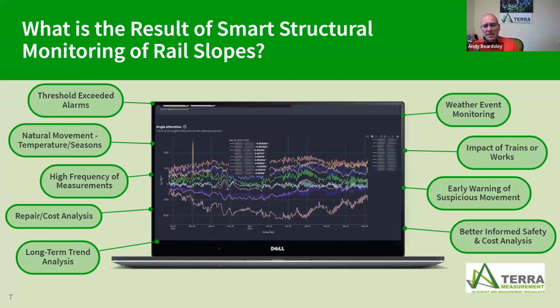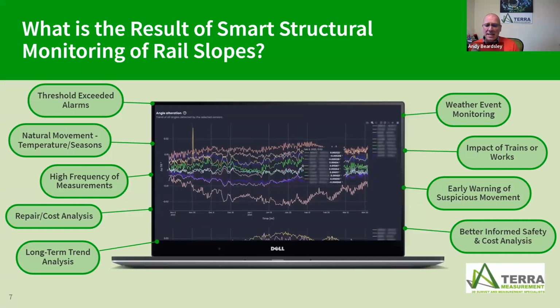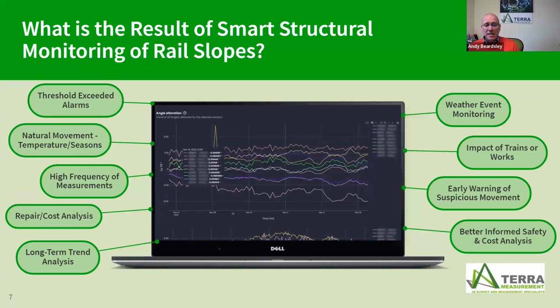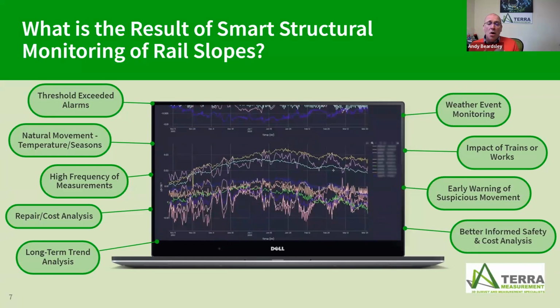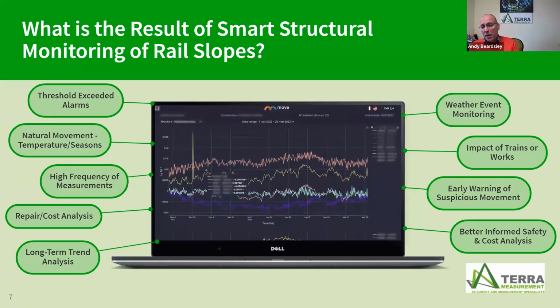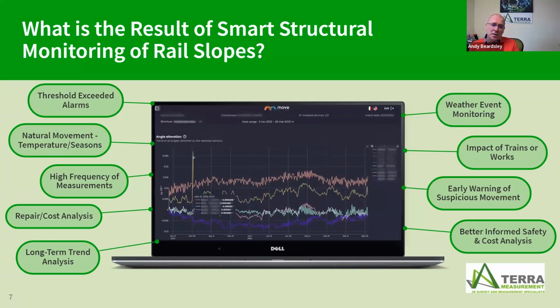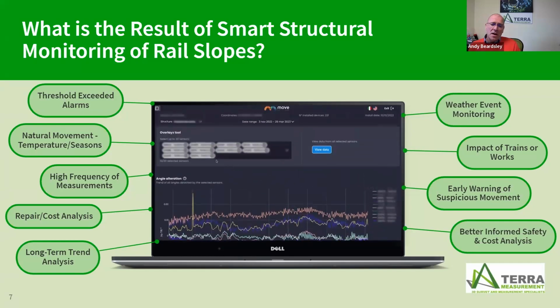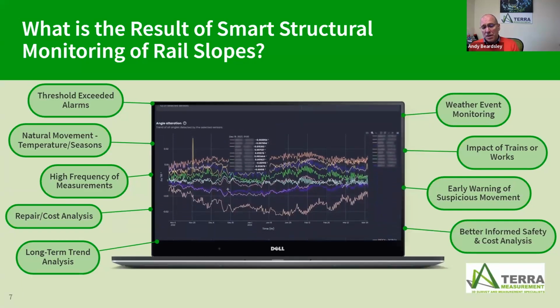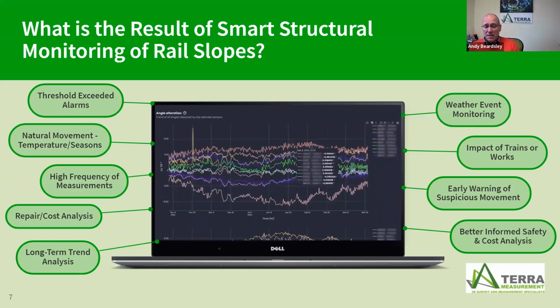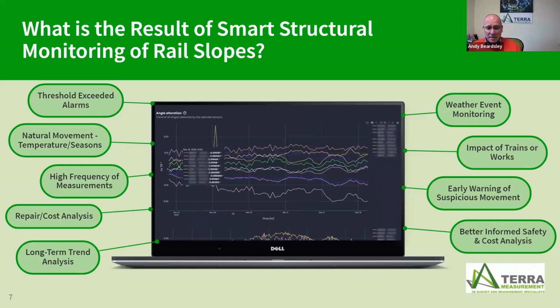Number 3, there is a subsidence alarm system at the site detecting at 2-minute intervals for the worst case scenario of track damaging landslip. This solution is provided with the concept of the Internet of Things. In this case, it is comprised of wireless LoRa and tilt sensors and the data gateway on site, rapid data transmission to the server system, and then rapid deployment to the cloud-based software platform. The advantages of high-frequency data and analysis, the subsidence alarm system, the significant reduction of site visits make for a very cost-effective system that can inform Network Rail asset teams better than ever before.